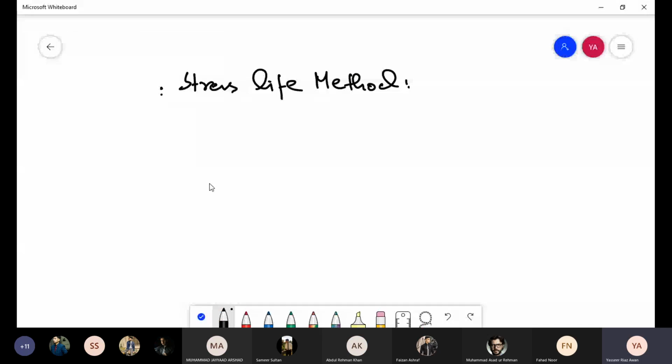In the case of fatigue, the strength value is usually the endurance limit or fatigue strength. Now there is an endurance limit or fatigue strength value that you get from tests, basically the R.R. Moore rotating beam test, and we call that Se prime. Then to get the actual Se, that is for the parts that we design, we multiply this with some modifying factors.